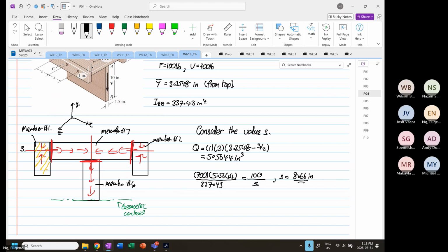Now consider S prime, which is the vertical nail. So what did the rule say? The shear flow must distribute in the entire member, then you transmit. So this is what's going to happen. Over here, it will distribute the whole thing first. Then it will transmit to the center web, the whole thing. So that is the entire area you have to consider.